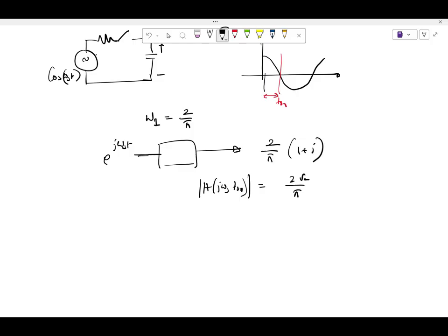can you comment on the fact that if RC time constant is very high, what should the output waveform look like for any particular input, let's say a cosinusoid or a sinusoid of any particular frequency? The frequency is not changing. Input frequency is same. It might be omega s, might be multiples of omega s, might be anything. But what should the output look like? It should look like flat, right?